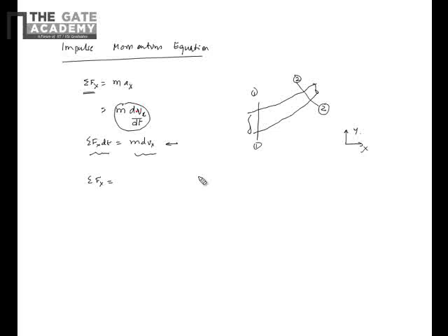Once you apply all that control volume system approach, what we get is rho Q, the mass flow rate, into final velocity at section 2 minus initial velocity in the same direction. So mass by time becomes mass flow rate, and the change in the velocity is v2x minus v1x. So this is the force that is acting on the fluid between section 1 and 2.